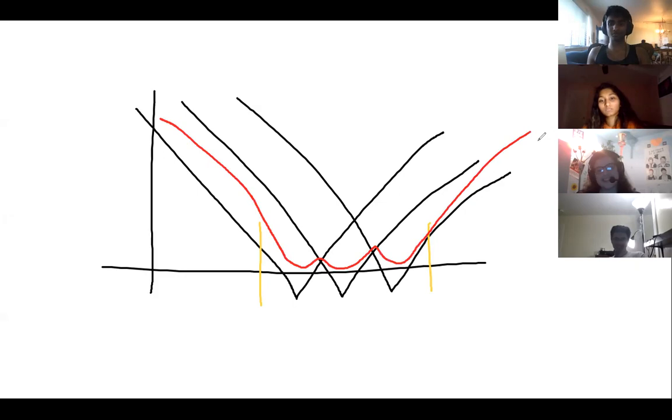That's nice. Would you put these capacitors specifically for decoupling or bypass capacitors? Yeah, or I mean, I guess it could. This is more useful for input and output capacitance on a power supply. Most chips and ICs need one capacitor for decoupling or bypassing because they're expecting most of the filtering to be done on the power supply side. You could put a ton of capacitors everywhere, but that just makes design harder. You need more space.